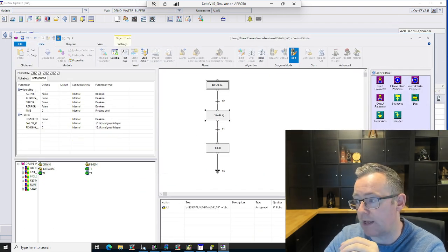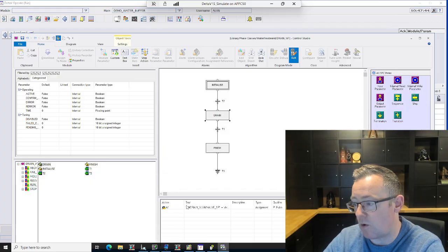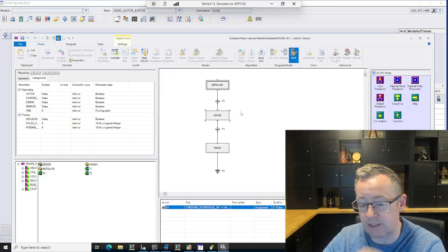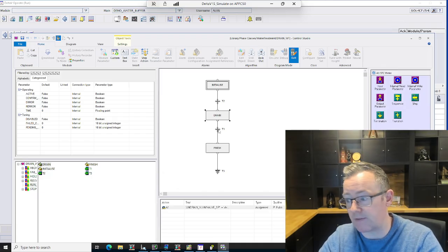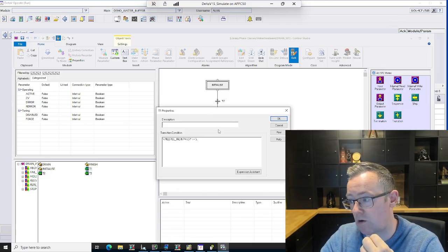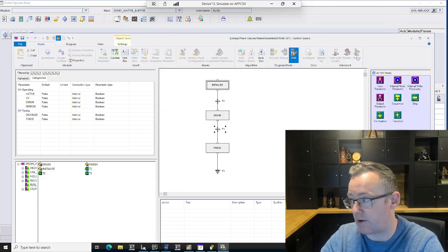And if you go inside here, what you'll see is that in a sequential function chart, we have small bodies of logic placed inside each of these individual steps, and then we have a transition, and that's effectively it. We have an actual transition that makes sure, for example, that we can't go further or not, right?